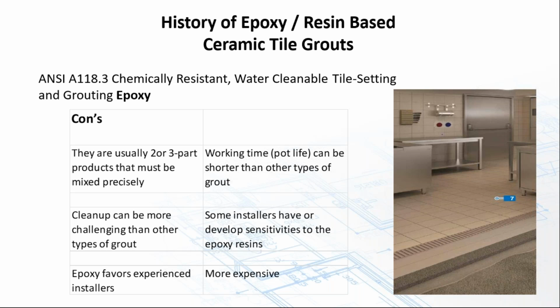The other important thing is, as you're doing a couple of units of epoxy, clean the bucket before you start mixing another unit into that bucket, or use a fresh bucket, because the residual from the older epoxy that you used 30 minutes ago is setting up, and that will also cause the newer epoxy to start setting up faster. So either make sure that the bucket is completely clean before you mix into it again, or use a fresh bucket for each batch that you're mixing up to give yourself the proper working time.